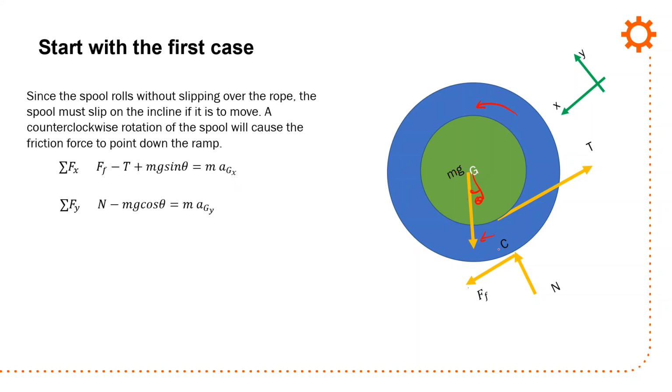Next thing is the normal force, which is acting upwards. I have the weight component, which is acting downwards, and that's mg cos theta. And finally, I have the force of friction from the outer spool, so it's causing a rotation in the clockwise direction. I have tension in the cable times R inner, and I have I_G alpha of the spool.